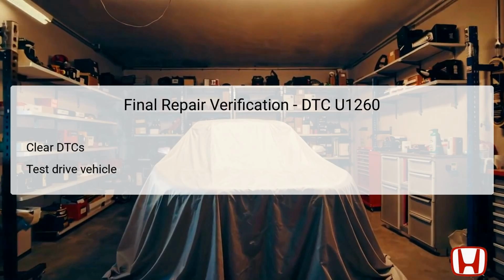After completing the troubleshooting steps and conducting necessary repairs, the final verification process involves clearing any stored DTCs from the system using the HDS. Once cleared, conduct a thorough test drive to evaluate the performance and ensure no DTCs reappear during operation.